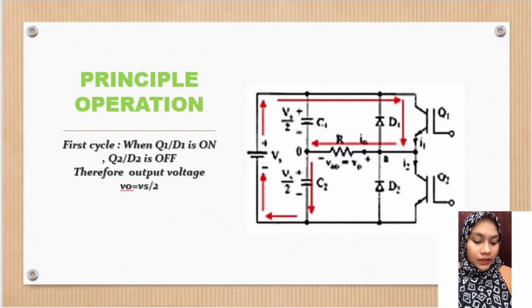This allows the CCV to operate in 4 quadrants. The 4 quadrants are: positive V and positive I, and negative V and negative I in rectification mode, and positive V with negative I, and negative V with positive I in inversion mode.